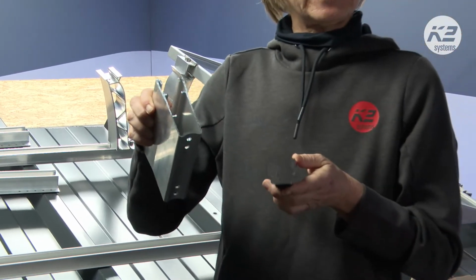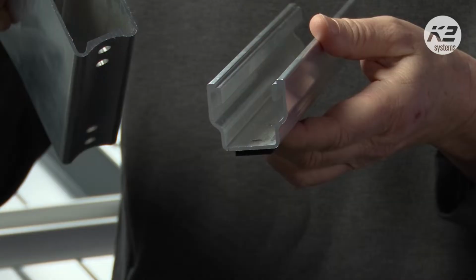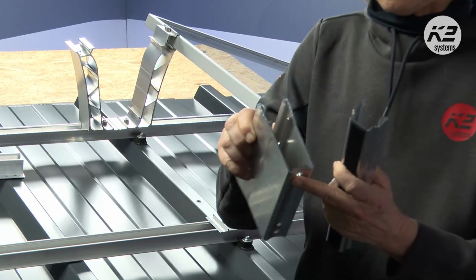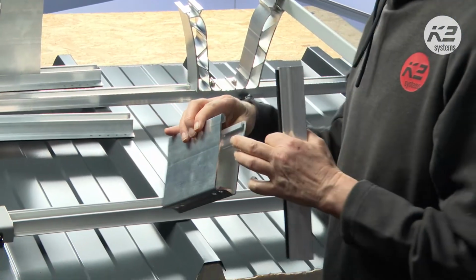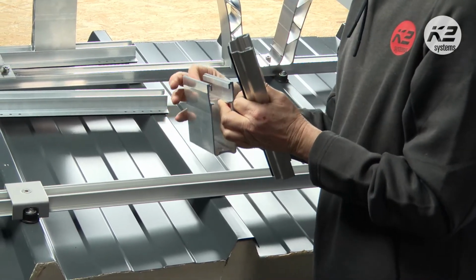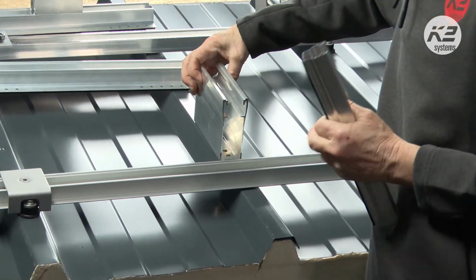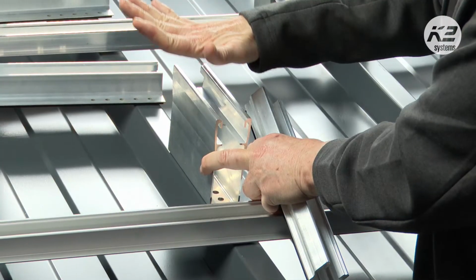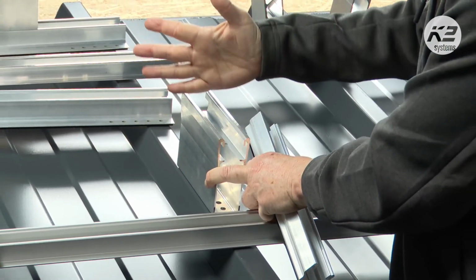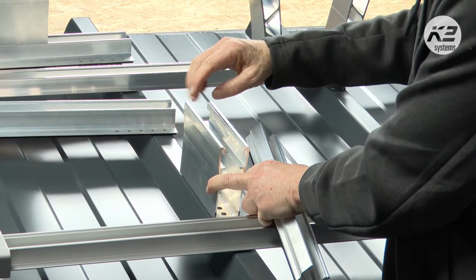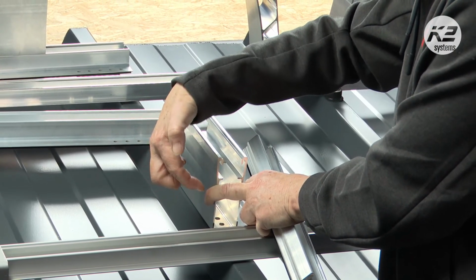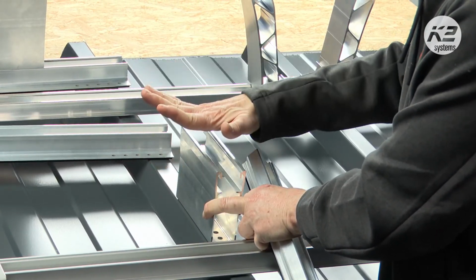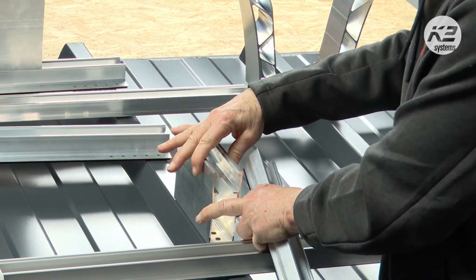Okay, the flat one is that one. And this EPDM sealing, if you buy it, is already also there. It's just an example, yes. But the system is the same. You install it later on the crest, and install the modules up there with the module clamp, in a landscape way, and so the modules are lifted around 10 centimeters from the surface of the roof.